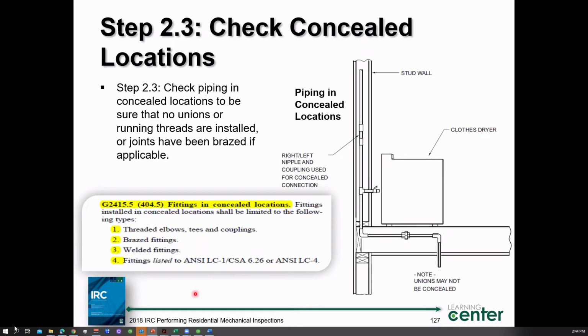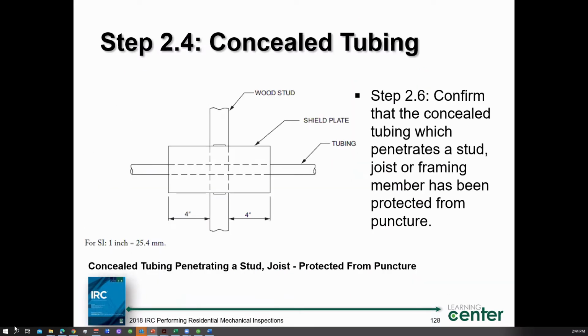You've got a nice system. So inspectors, when you're out there looking at this proprietary system, you need to look at the manufacturer's installation instructions for CSST. We'll talk a little bit more about that coming up. Yeah, there is a manual available for that, where it tells you about those protections and everything. I have that manual. Each manufacturer has their own manual, correct. And you could actually size that stuff as well, according to their manual.